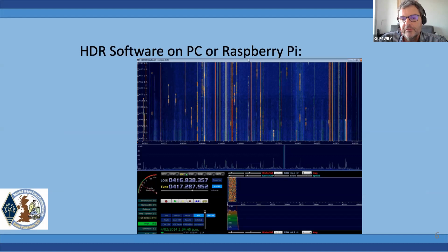The advantage, of course, is that you can see immediately here that you can have a look at the whole band, or a big chunk of the band, which allows you to see signals and locate signals in the band. The little Minion SDR that I showed you, by the way, does have a waterfall and a spectrum display on that tiny screen. And that's really one of the advantages of software-defined radios, that you can have all those extra features that the regular radio wouldn't have.